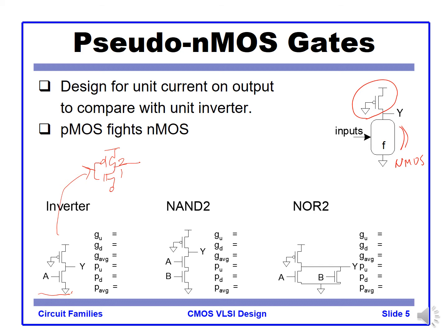Let's say we start with a 1, and 1/4 would be 0.5. For a typical inverter the PMOS size is 2. We want that to be 1/4 of the original, which would be 0.5. So in this case, what would be the effective pull-down driving strength?